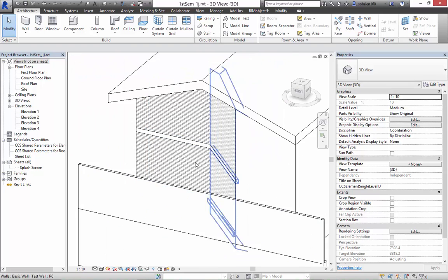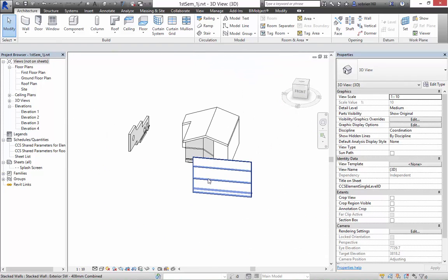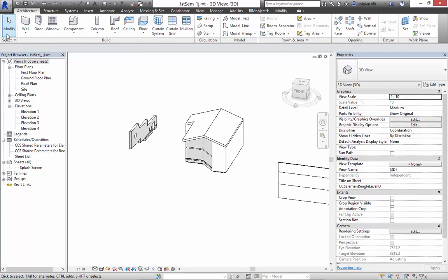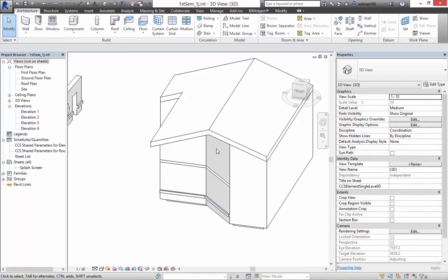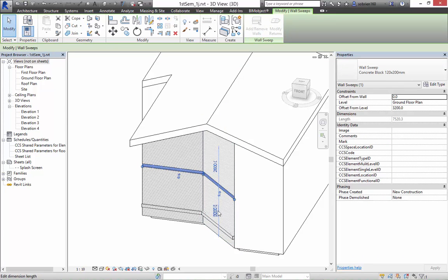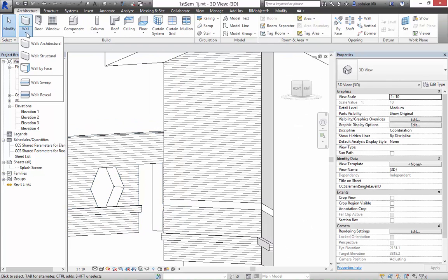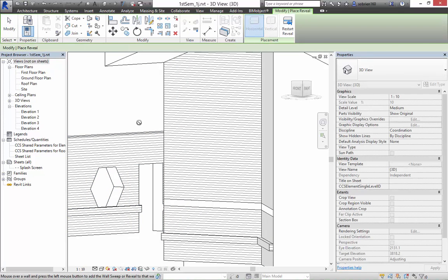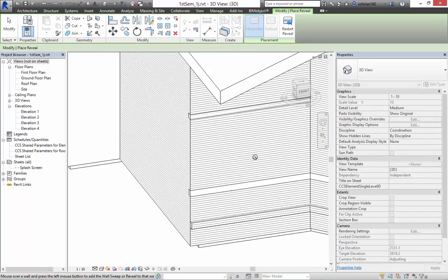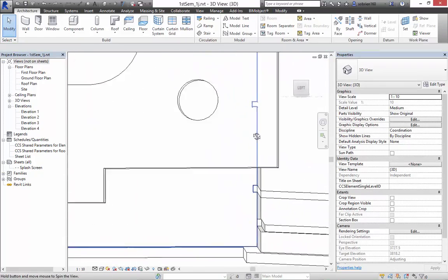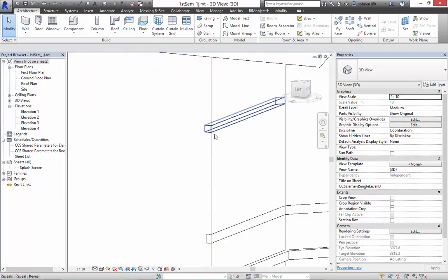But then you can select the height and so on. Yeah. If you do it like this, where you just use the wall tool, you can select it afterwards. You can delete it, or you can change the position of it to whatever you want it to be. But what I don't understand is it doesn't seem to be actually taking. Let's try wall reveal. There it is. Okay. Now we got something going on. So that's what a reveal is. Yeah. A bite out of the wall like that.